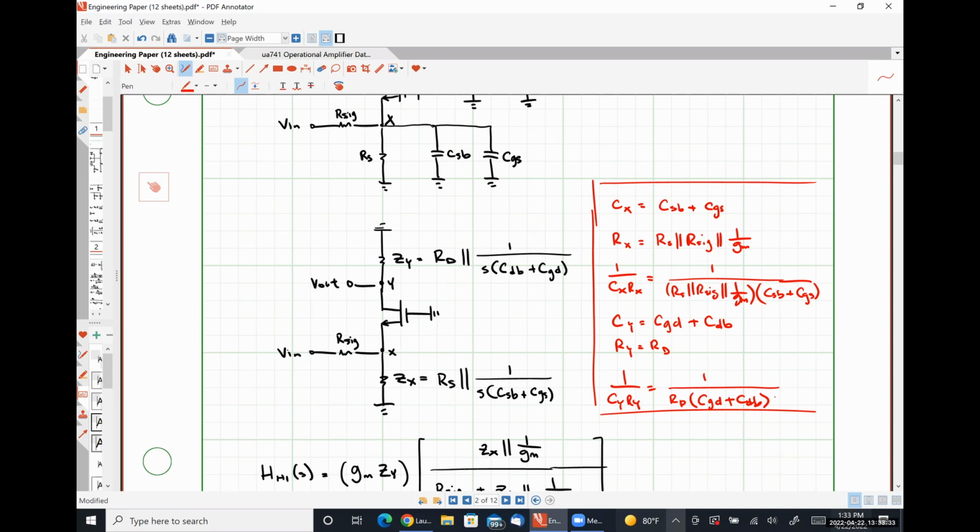We absolutely have to consider that VN is grounded out, which is how our signal source here looks in parallel with anything else, because we're determining effectively the resistance or the equivalent impedance seen by this node, or the equivalent resistance seen by this node and the equivalent capacitance seen by this node.